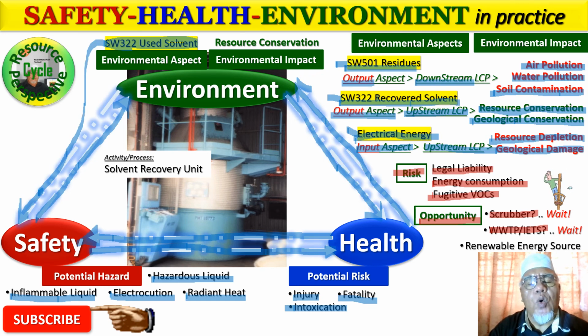What is the best adsorbent for volatile organic carbons? Some of you know this. Those who have attended my training before have done it. I think you know about activated carbon. It's made from plants, shells of coconuts, even kernels of palm oil, and even bamboo. It's not about what it's made from, it's how to make it. So maybe we can use it as an adsorbent. It is able to absorb all this volatile organic carbon and prevent us from building a scrubber, which would eventually lead to the need to build another system, which is wastewater treatment plants.